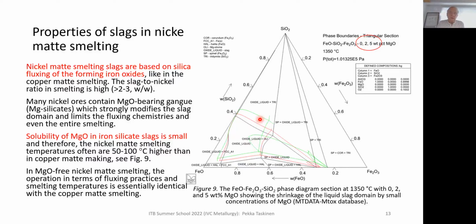It may be a two-phase slag with some solids in it, and this means a longer tapping time, and in the worst cases the operation is actually limited by slag tapping.